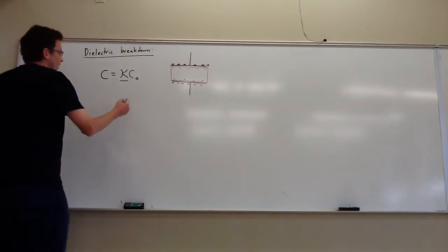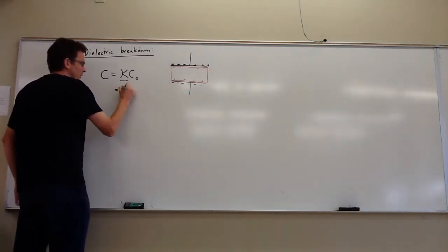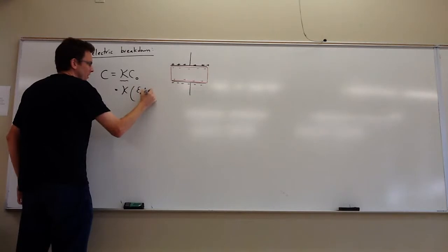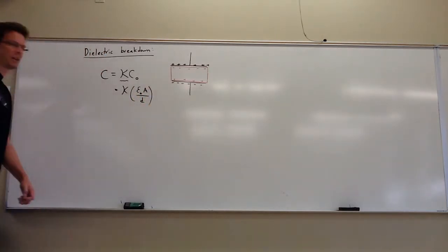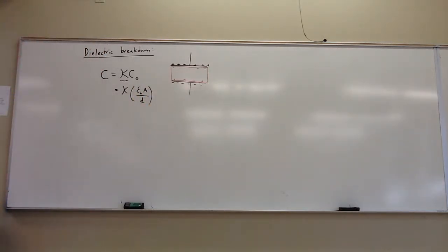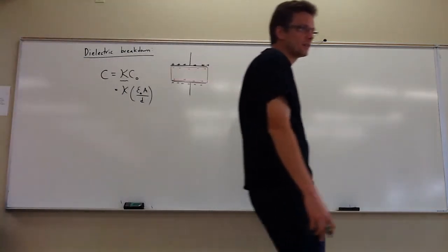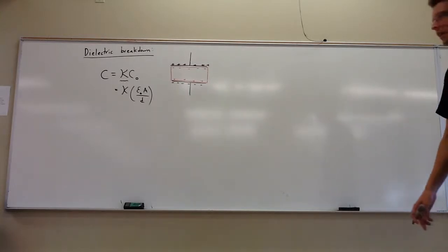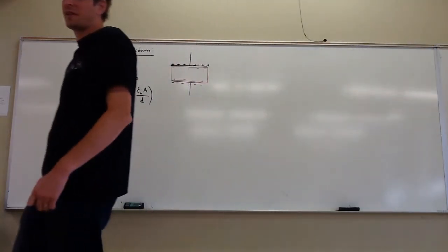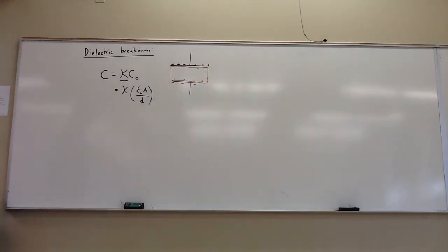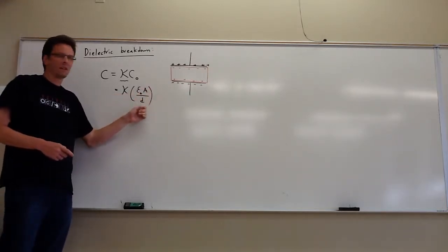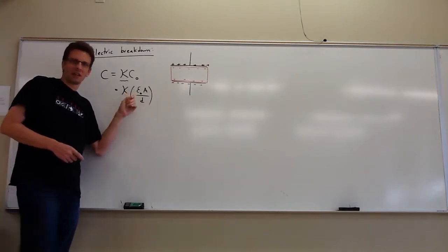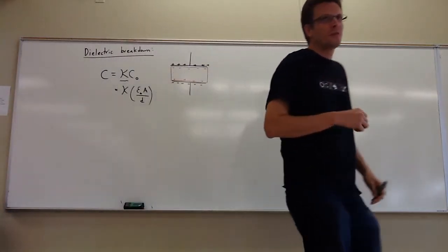And then, for a parallel plate capacitor, what is it that determines the capacitance in the first place? We learned that the area of each plate and the plate separation determine the kind of baseline capacitance before you throw in the filling, the dielectric. And so what I wanted to do today was carefully look at each of these terms. There are 3 active ingredients, kappa, A, and D. Remember, epsilon is a constant, okay? So you have 3 different options to improve the capacitance, okay?